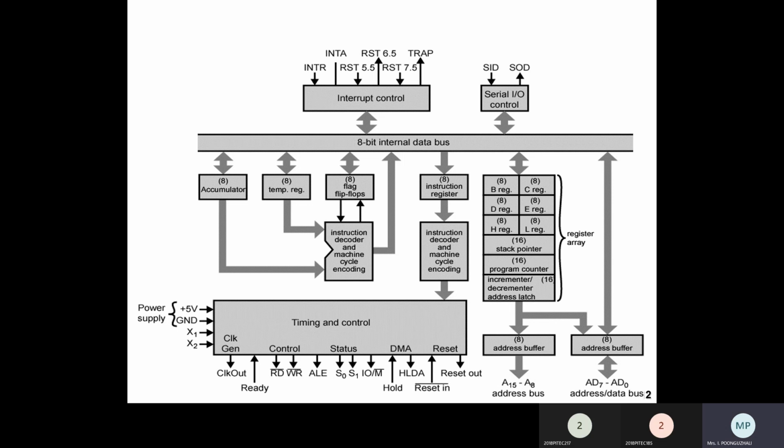So after executing that part, at the end I will have a return instruction. On seeing the return, again I have to take what is in the stack pointer and place it in the program counter now. I have to save the address where I stopped, then only I can come back and execute from that point. That address is stored in the stack pointer. After executing the subprogram, on seeing the last return instruction, I have to take the content, that is the address held by the stack pointer, and put it back in the program counter.